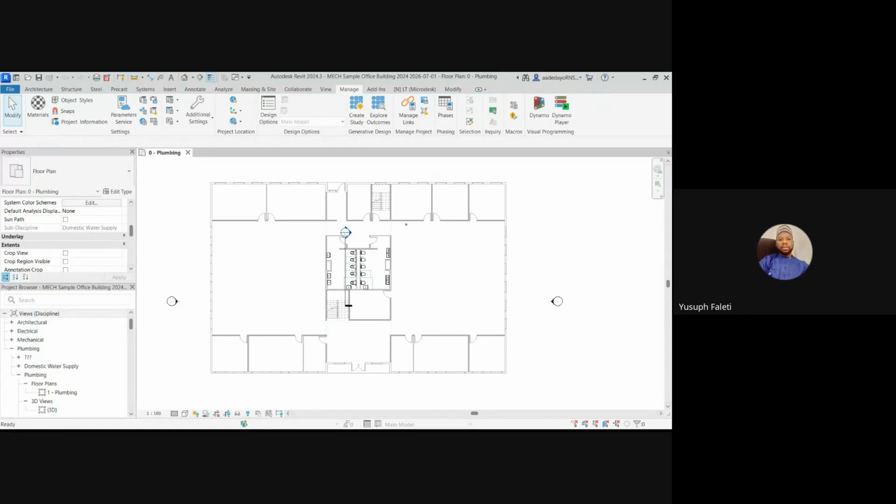Okay. So it now brought another thing. Autodesk Revit 2024 warning: the link cannot be reloaded because it is loaded into another open document. So that means you have that drawing open somewhere else. You need to close other drawings that have that link, that same architectural Revit file open. So just make sure you have only this one we are working with open.